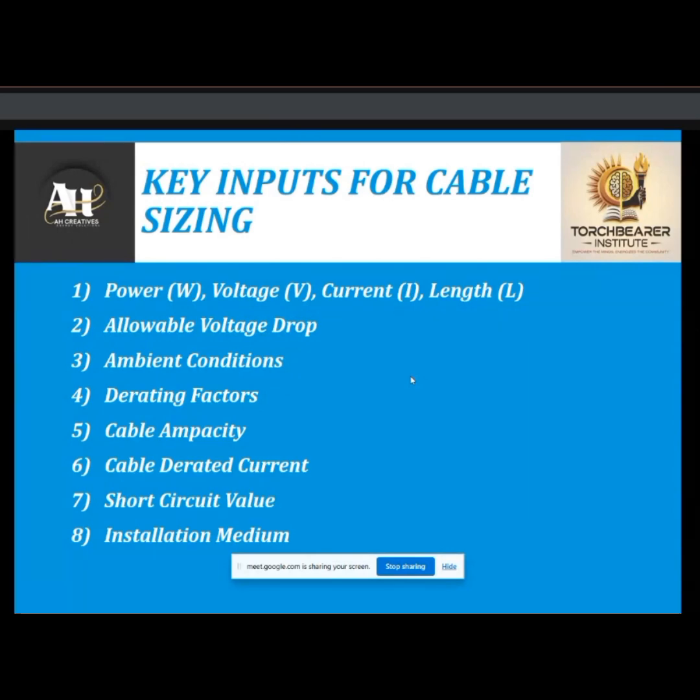Voltage drop, I have already explained that for the cables, the allowable voltage drop for the DC string is between 1 to 1.5%. For the AC cables, basically the IEC standard allows us 3 to 4%. But due to the different limitations of different clients, there are some clients on the stricter side, and they allow us a voltage drop for the AC cables of 1 to 1.5% maximum. That's why, to give the performance ratio on the higher side.